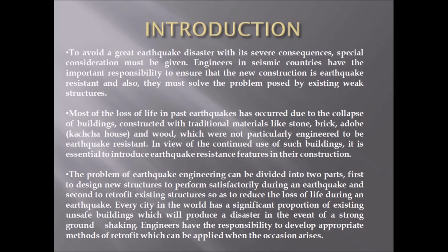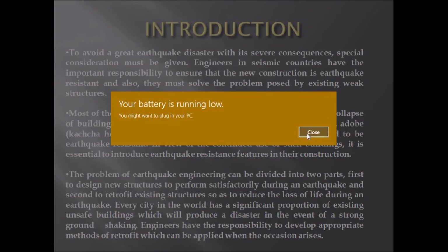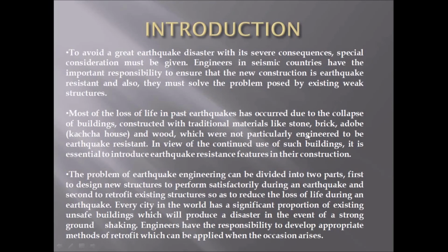Most of the loss of life in past earthquakes has occurred due to the collapse of buildings constructed with traditional materials like stone, brick, adobe, that is a kacha house, and wood, which were not particularly engineered to be earthquake resistant. In view of the continued use of such buildings, it is essential to introduce earthquake resistance features in their construction.